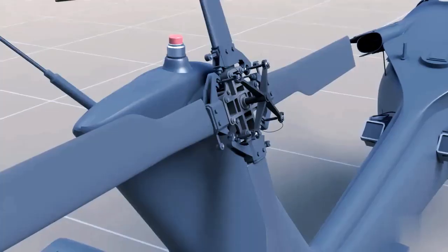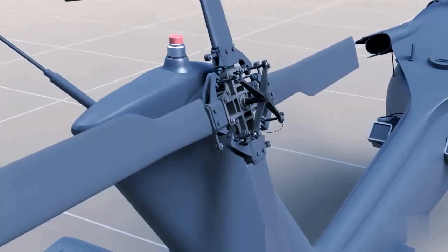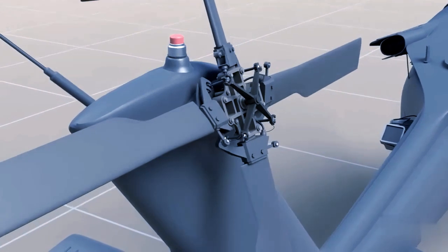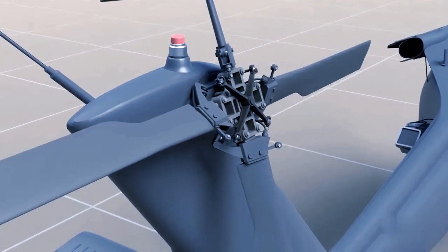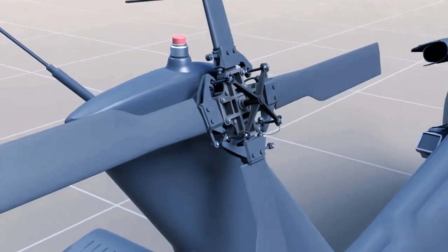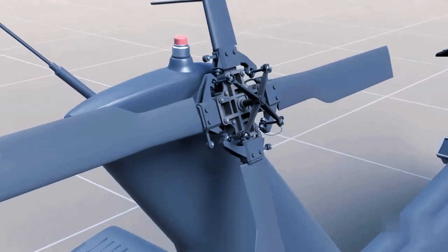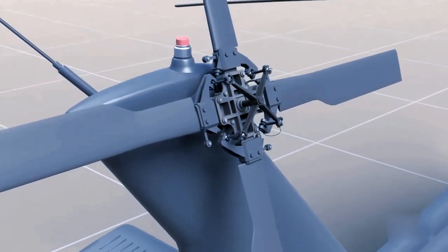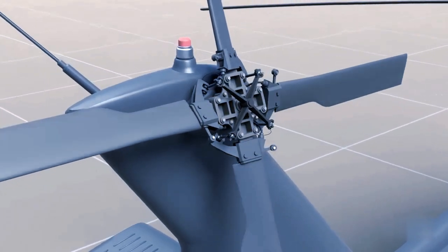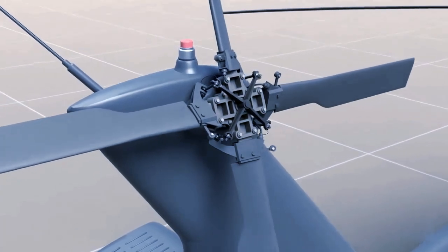This is a 4-bladed tail rotor on a Sikorsky HH-60 Pave Hawk helicopter. This tail rotor has open-tipped blades that are variable pitch, and the helicopter's anti-torque pedals, which are positioned like rudder pedals on an airplane, control the amount of thrust they create.